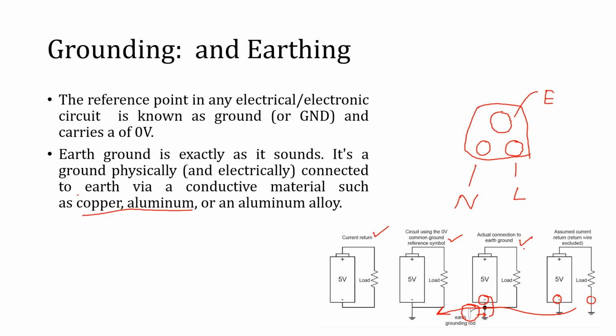So these are some of the configurations we use in signal conditioning and data acquisition, and a transducer must be connected in such a circuit which should be at least grounded with the power supply. It should not be a floating circuit like the first example. We'll see what the disadvantages of these circuits are in the next slide.